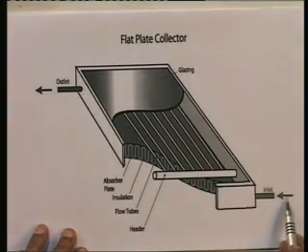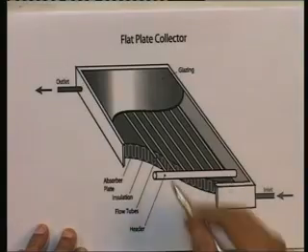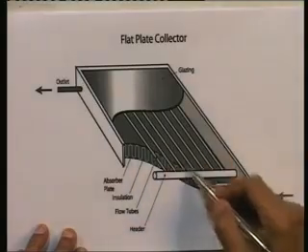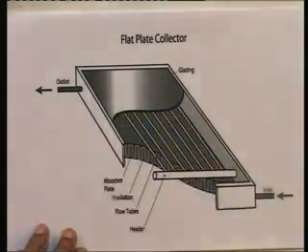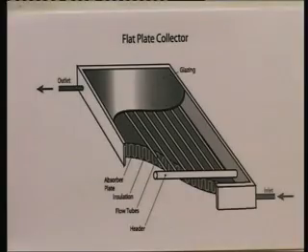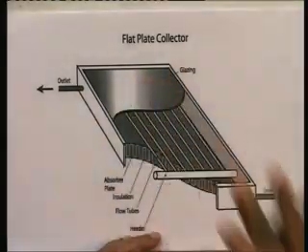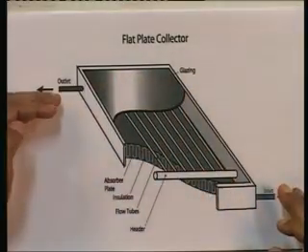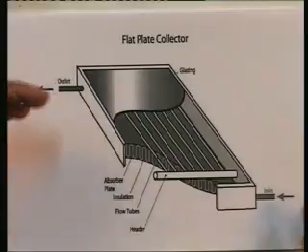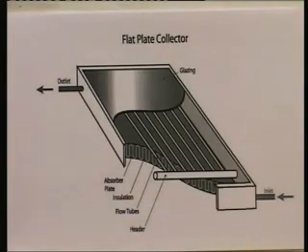So, it enters here at the point which is called the inlet, flows in this header which I am pointing out here, then gets distributed in these flow tubes and then goes out through the outlet header. Right, that is the position. So, the solar energy falls on the flat plate collector, and the water as it flows through gets heated up, and typically as I said, you can get hot water at temperatures like 60, 70, 80 degrees centigrade in this collector.